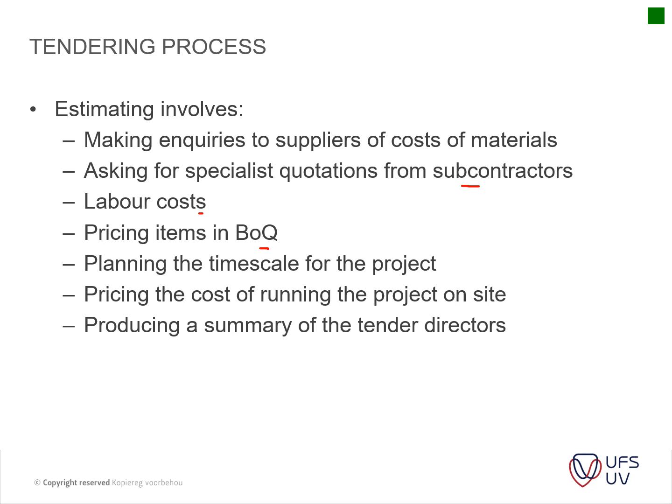Planning the timescale for the project. This is mainly for the P's and G's to be able to price that. So for instance, if you've got a crane on site, how long will that crane be on site? Cranes are usually charged per day, with an establishment cost, and then the cost per day is usually calculated on top of that. So you need to get a realistic timescale for calculating your P's and G's. How long will your insurances be running on the project? How long will you have containers on site, etc.